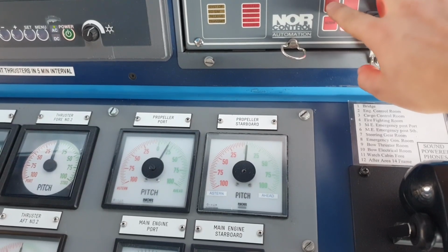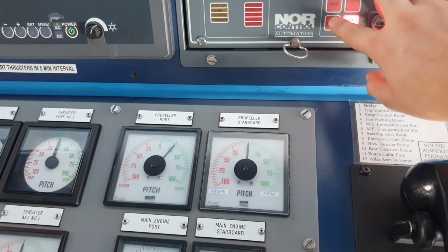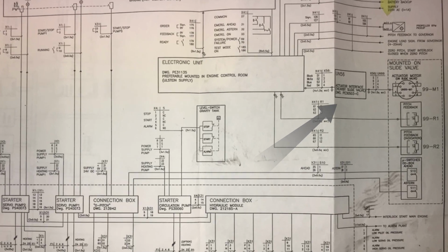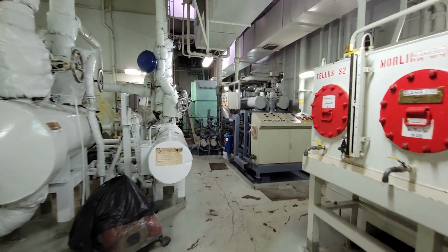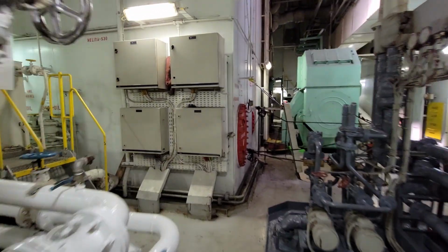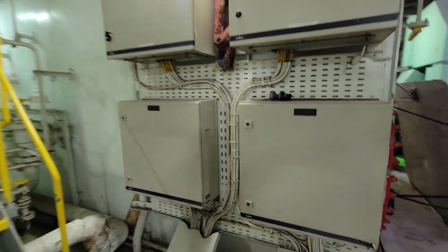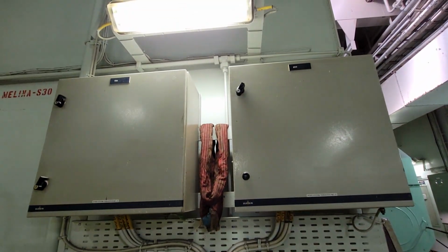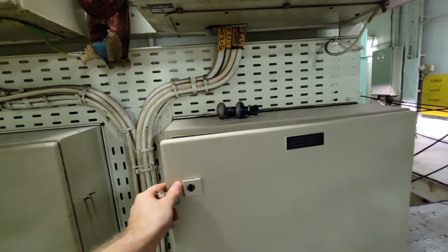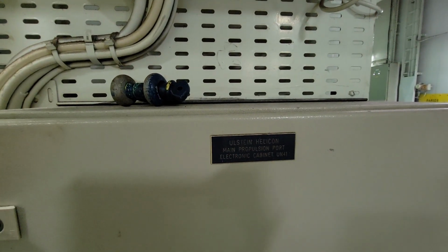Alarm CPP control failure still present. How can we see from the diagram that the wires from the switchboard where the stepper motor driver is installed go to the control panel switchboard with electronic control boards and the micro terminal for system diagnostics. This electronic switchboard is mounted near the engine control room, 2 upper ones for stern thrusters, 2 lower ones for main thrusters CPP. Open the door and see an error on the micro terminal: DP pitch order.